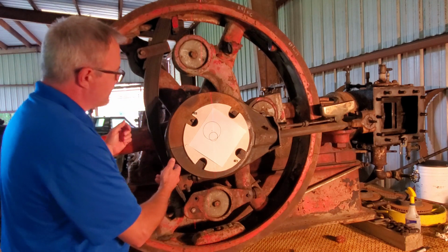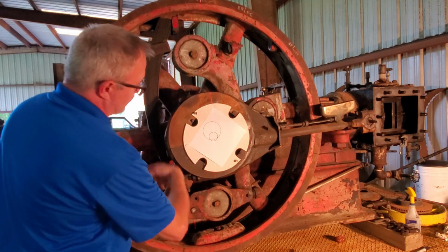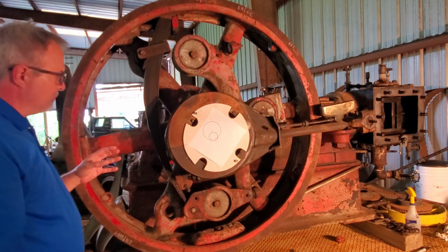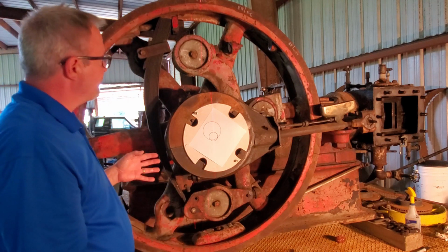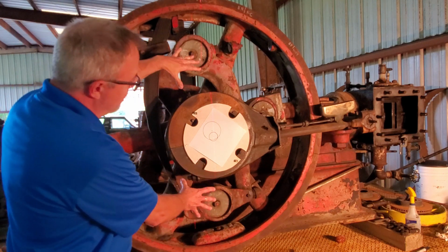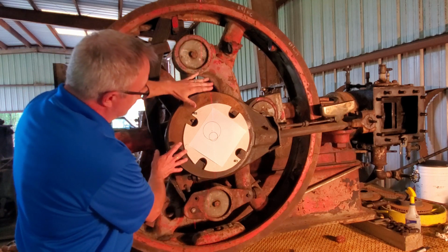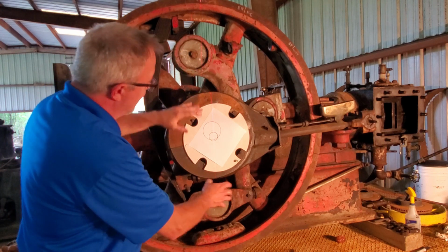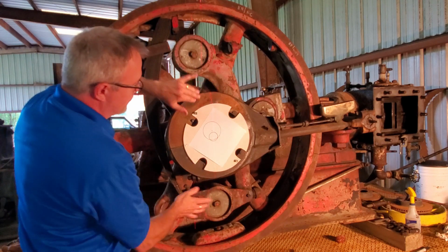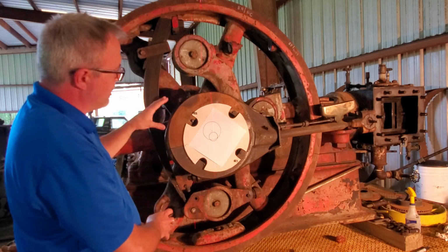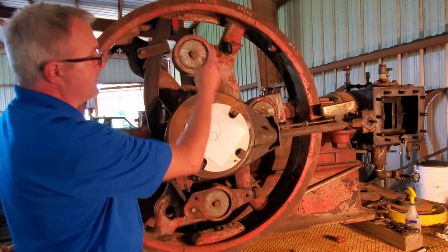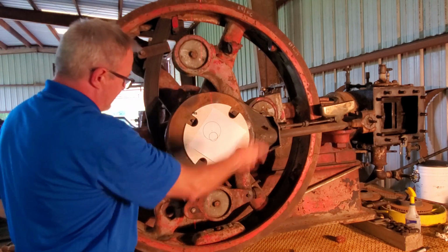Now this engine, as we're looking at it, has a normal direction of rotation that is counterclockwise as viewed from the flywheel. But in order to reverse the rotation of the engine, what you do theoretically is you take the entire governor mechanism off. So you would take the eccentric rod off, then the entire governor could be disassembled, flipped 180 degrees, and rebolted back to the flywheel. And that would shift the lead 180 degrees from where it is, and then the engine would run in the opposite direction. It would run clockwise.